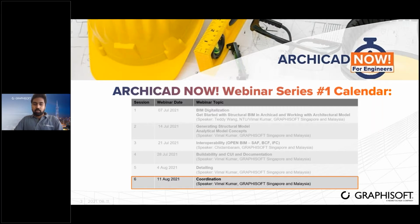And finally, on the fourth session, we saw buildability score for BCA and also for Malaysian standards, to calculate the B score in BCA buildability format, and then the IBS score for Malaysian standards. And also we saw how to compute the concrete usage index from the Archicad model, and then we saw how to publish the model using the publisher or in the navigator.